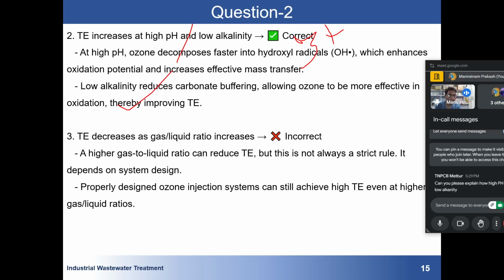Yes. Now we will be looking at the rate at which we are decreasing the pH or decreasing the alkalinity. Imagine that the amount of carbonate and bicarbonate present in your system is very low, but somehow with the help of OH minus you are increasing your pH. So the amount of alkalinity will also increase, but the increase will not be so comparable as in the presence of carbonate and bicarbonate.